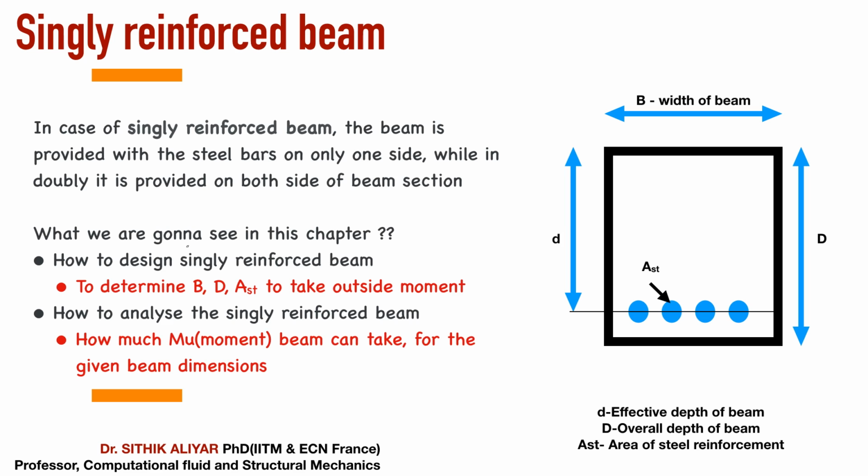Consider if you are sitting in your house listening to this, you see the top corner, you just lift your head, turn right or left to your top corner, that is the beam. Okay, hopefully if you are in a residential building, it will be some 300 cross 300, 300 cross 400 beam. That's what you are seeing above the windows. Mostly the residential buildings will use some 16 mm bars or 20 mm bars.